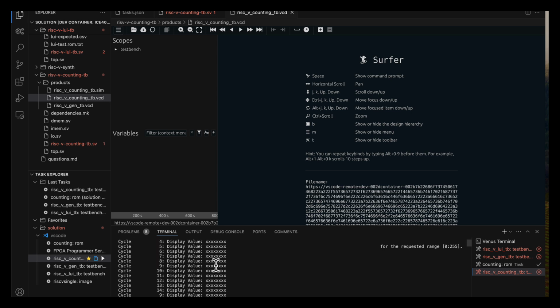After about 14 clock cycles, approximately 14 instructions worth of time, we get to the point where my code has finally initialized that counter, and it's already made its first count because it starts by counting up. We can also see that my code spends from clock cycle 15 to clock cycle 26 at count 1, so it takes around 10 to 11 clock cycles to go through a full loop where it updates the counter. As time goes on, the counter counts up. So I've verified that my code is doing the counting up part.